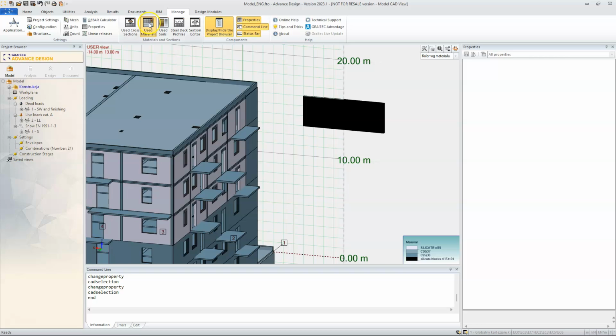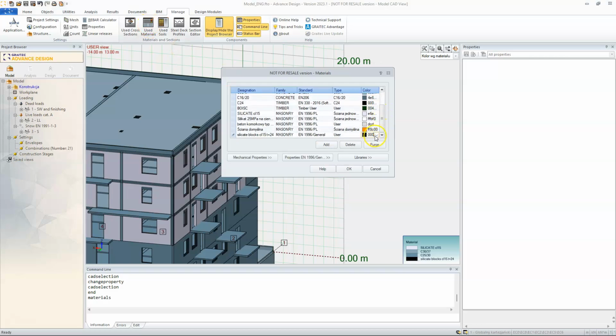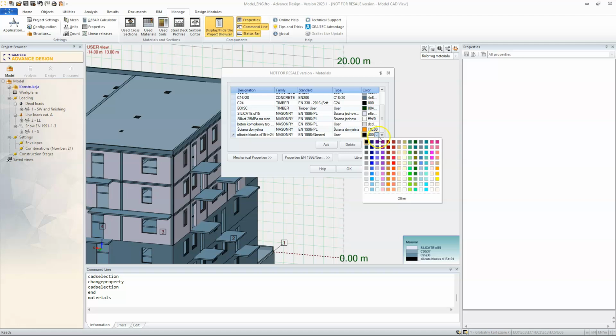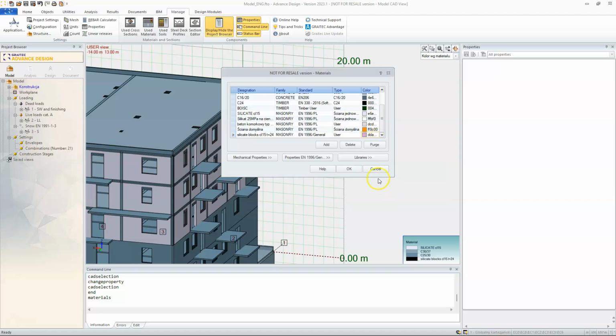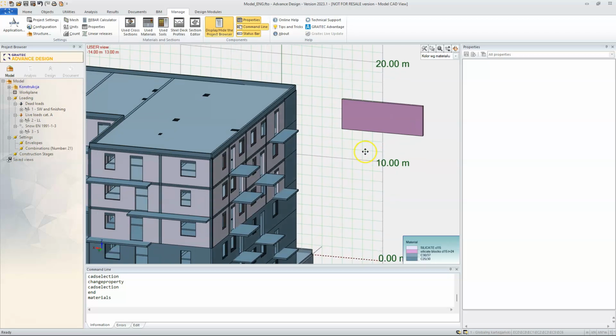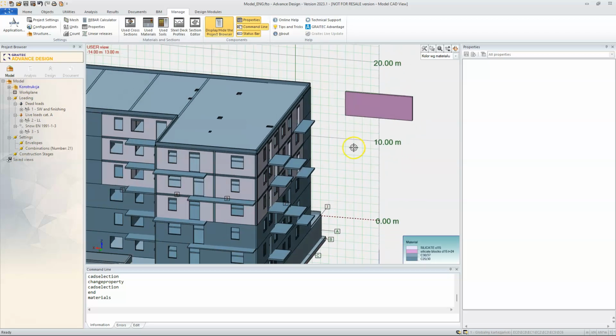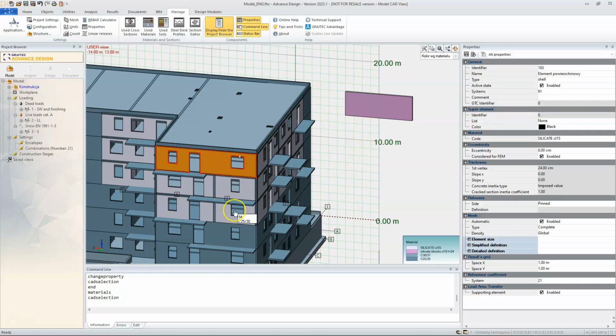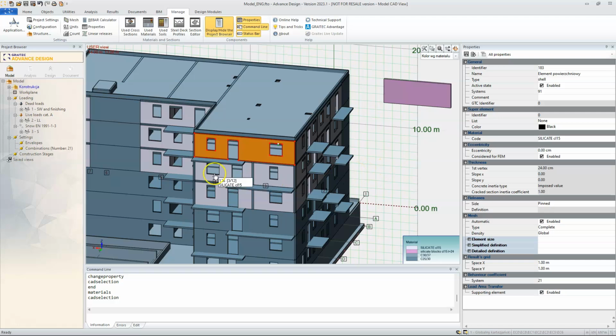Of course, I can change the color to distinguish better the materials provided in the model. Let's say I will right now stick to something else than black. If it comes to modeling of masonry walls, what we'll have to design is actually some panels. So usually between the openings, we will design each panel separately. But you don't have to divide the element to make them separate.